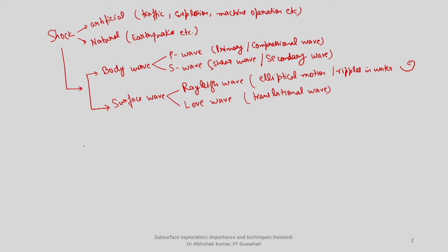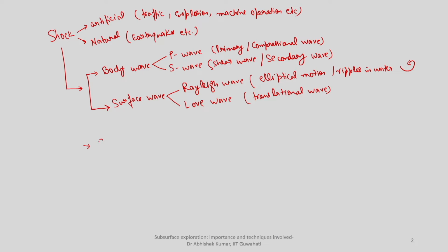But most of the time, when interpreting the subsurface medium, we are interested in finding the shear wave velocity, because that gives an indication of the shear strength of the material, which is more important, particularly for seismic scenarios. Shear velocity can be directly quantified for medium identification.